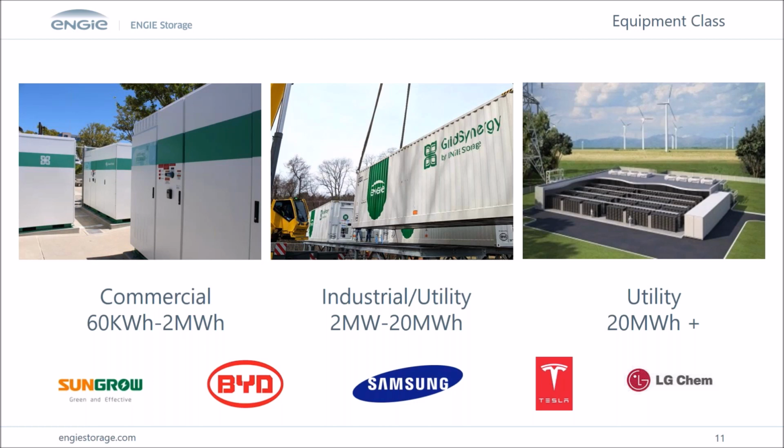Financially, on paper, it looks great to put, let's say, a 100 kilowatt system on a 2 megawatt load, and you're getting almost 100% utilization and reducing demand charges. The problem with that is it's very rare you can predict the exact kilowatt maximum per month per period. And so your risk is significantly higher, where if you miss 5% of a 2 megawatt load with a 100 kilowatt system, you've wiped out all your savings for the month. So sizing is another critical piece in order to reduce your risk and size it appropriately.